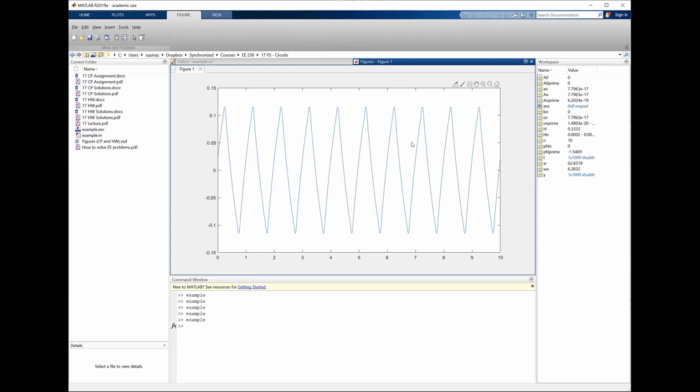This is a way that we can convert a square wave into a triangle wave, if you want to, by putting it through this circuit that we built that's clearly a low-pass filter. You'll see it cuts down our signal a lot. The original square wave went between -1 and +1. Now it's going only barely over 1/10 of that. But this is where the capacitor is charging up, and this is where the capacitor is discharging.